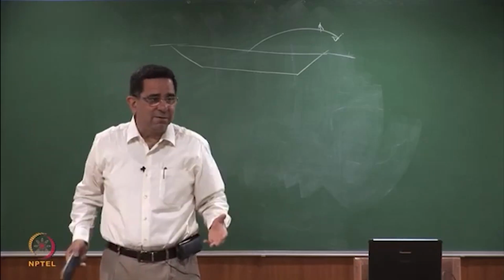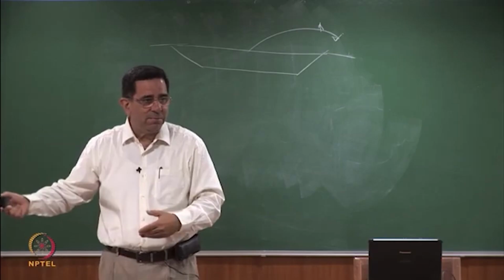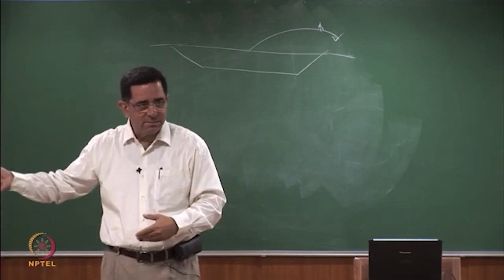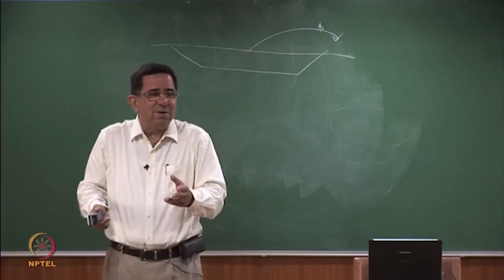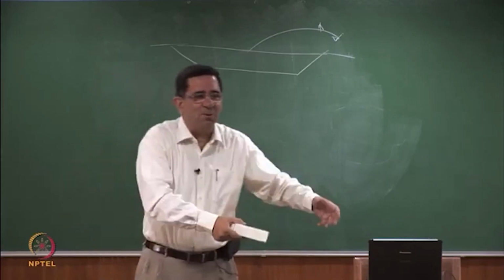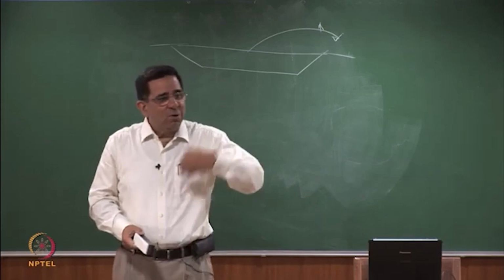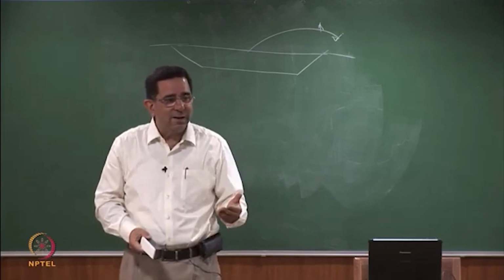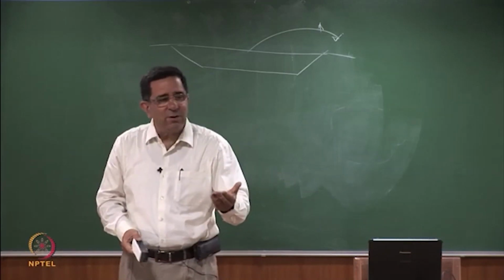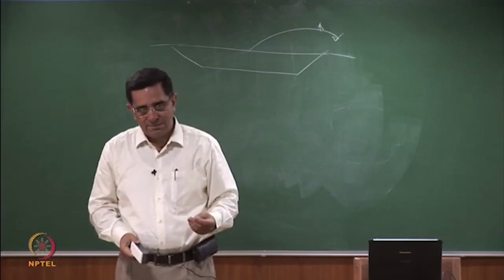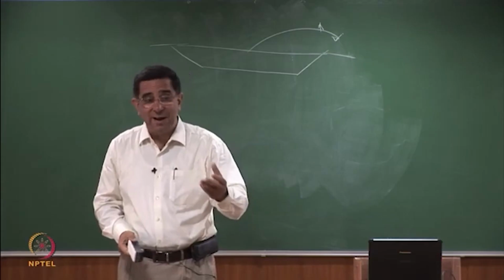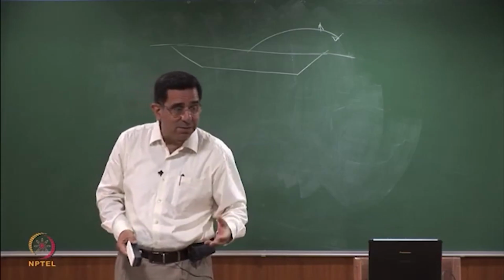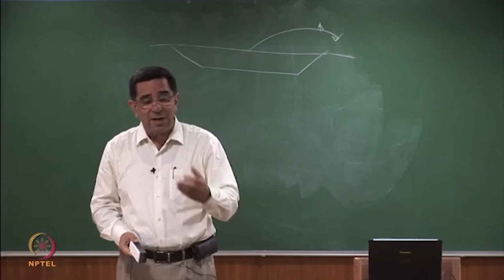Sand will settle very fast. You will decant the top, treat it, and you are not sure whether everything has come out. Take the sand again, put it in some more water. You will continue to do this till in the decanted fluid there is no contaminant. You can do it with sand or gravelly sand or sandy gravel because it settles in a few minutes. Now just take the opposite. I have silty clay.